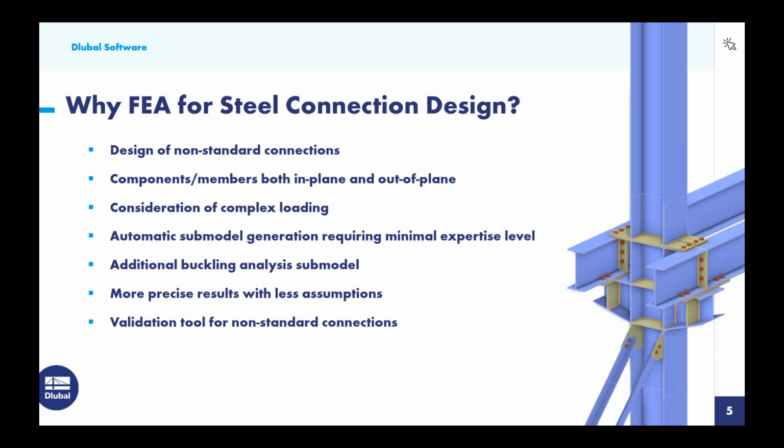We also will perform the AISC design checks of these connections for our bolts, our welds, and our plates, but we will take it a step further to create a second submodel to carry out the buckling analysis. So we'll be able to view the different eigenmodes and failure buckling modes of this connection, as well as the critical load factors. So we'll see that a little bit further in the example today.